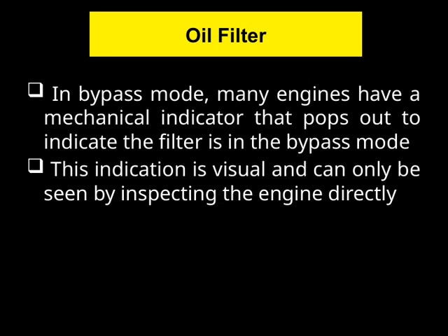When an engine is in bypass mode, many models feature a mechanical indicator that actually pops out to signal this condition. This is a handy visual cue because it lets you know immediately if the filter isn't operating as it should. However, it's important to remember that this indicator is only visible when you actually inspect the engine directly. It's not something you can see from a distance or through a dashboard display.